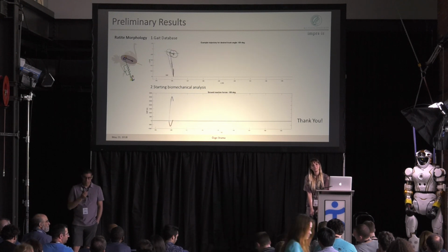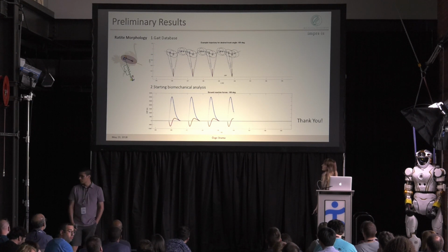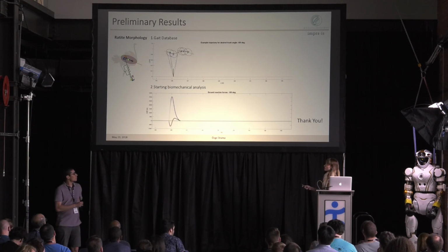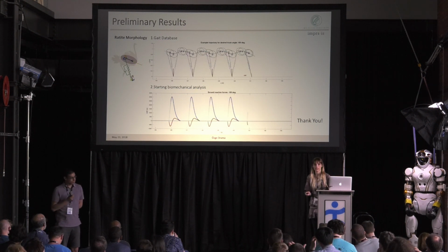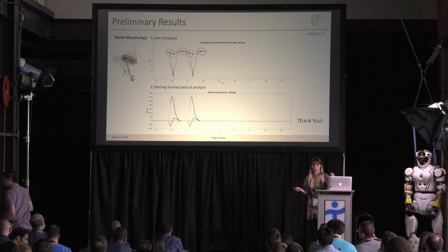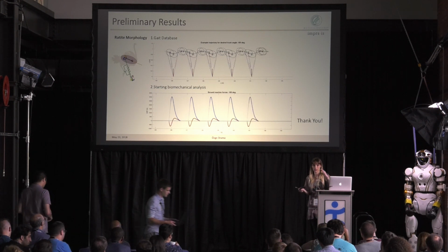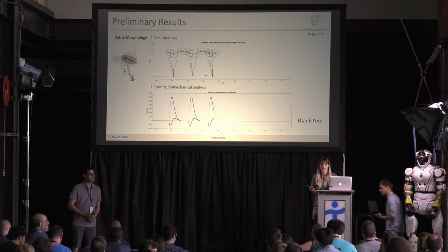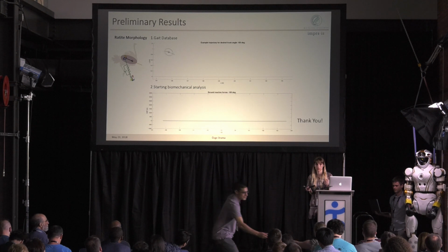Hi, how sensitive is this gait to that thigh length? If you make it so that your hip is much further or shorter from your center of mass, does that change the gait in any meaningful way? By thigh length, you mean the distance between the center of mass and the hip? Yep. I mean, the longer you make it, the harder it becomes to find solutions. So you probably need larger damping, which might be unrealistic, or larger hip torques. Do you know if there's a theoretical limit, or as long as you have the right control, you can? As long as you don't have torque limits on your motor, I would say.